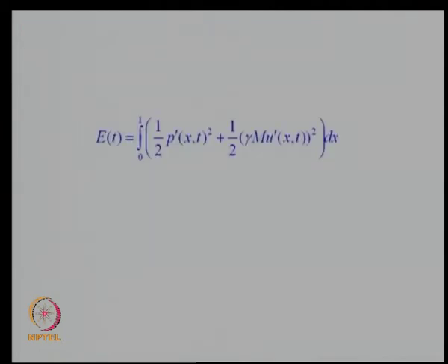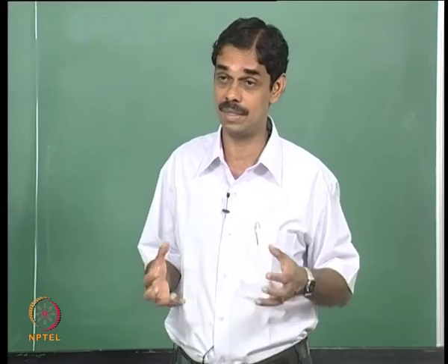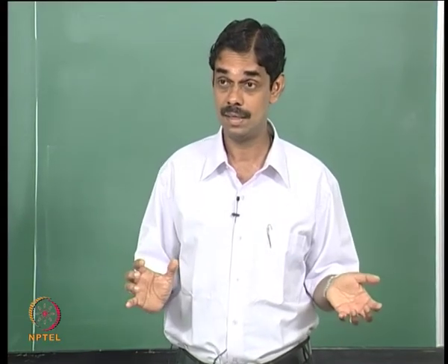So acoustic energy is a non-dimensional one, and of course when you non-dimensionalize, you can use different constants, so the expression you see in papers will change a little bit, but it goes like p prime squared plus u prime squared scaled by some factors. Now this norm is a constant times the energy, which is what we need. If you scale it some other way, you would not get it proportional to energy. So we have to scale it such that the norm is proportional to energy, then only the measure makes sense, because we are looking at the energy of the system.